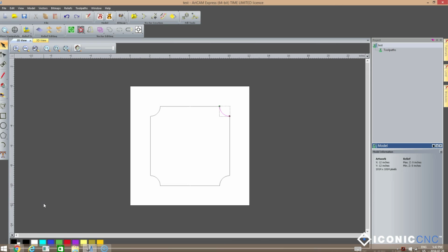The problem is that it creates a very inefficient toolpath because the tool has to keep coming in and out of the material, and also we will tend to see some dwell marks as that tool comes in and out. So it's not the ideal scenario when we're creating machine toolpath. So what we want to do is create a situation where all of these vectors are joined